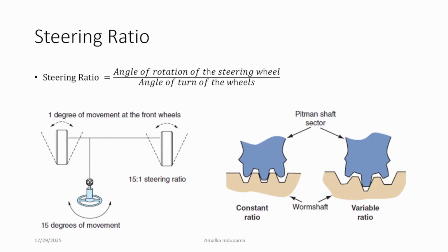Whenever the steering ratio is higher, the steering effort will be reduced, and the handling and the maneuverability will also be reduced, right? And also we have different gear geometries which will provide constant steering ratios and variable steering ratios.